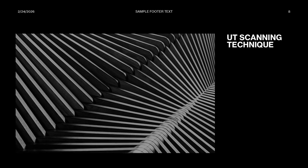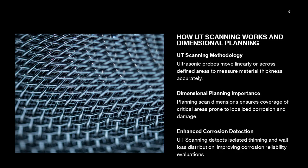How UT scanning works and dimensional planning: why, when, and where UT scanning is used. UT scanning involves moving an ultrasonic probe linearly or across a defined area to collect a series of thickness readings. This method can be performed manually, semi-automatically with encoded scanners, or fully automated depending on inspection needs. The typical scan width ranges from 25 mm to 50 mm, while grid sizes of 25 by 25 mm or 50 by 50 mm may be used for area scanning.